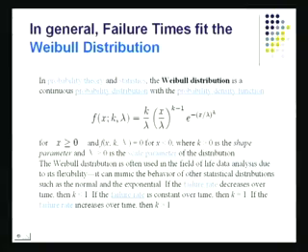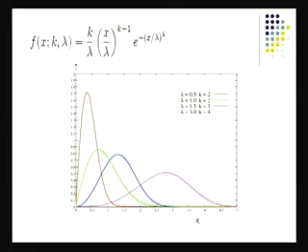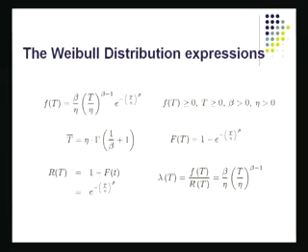These two ends are governed by what we call the Weibull distribution, and the Weibull distribution has its own peculiar formula. It also belongs to the exponential family. It's a very, very useful distribution. It can be specialized to a curve that is coming down. It can be specialized to a case when the curve is flat, the probability density is flat. It also can be used to show a rising or a deteriorating situation. All these three scenarios can be modeled by the Weibull distribution. So the Weibull distribution is a very, very popular distribution in reliability engineering.